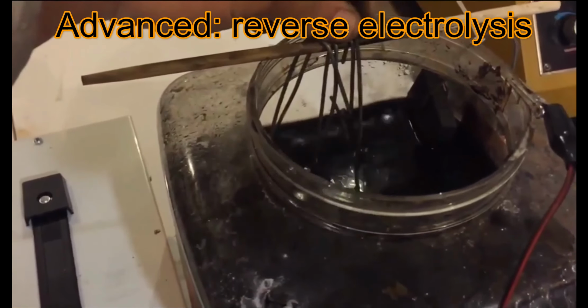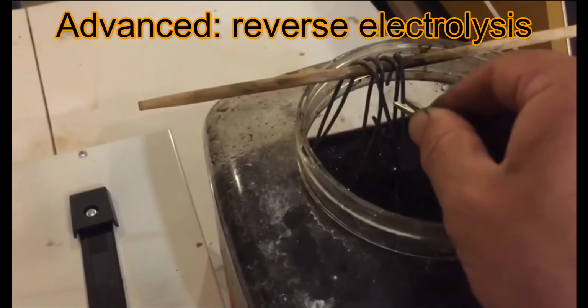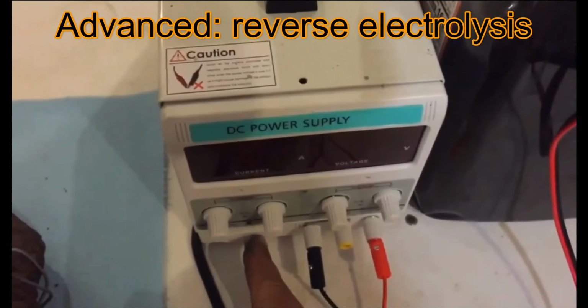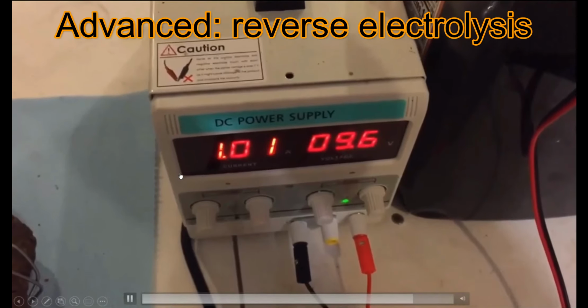And I'd recommend don't put direct fans or anything like that blowing on there, because you have a motor then running next to there that is a source of potential sparks. So you don't want hydrogen and sparks together.